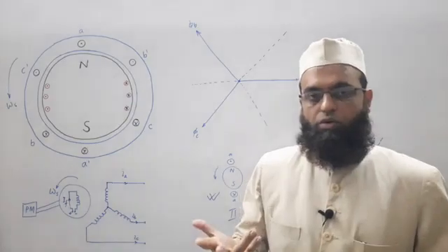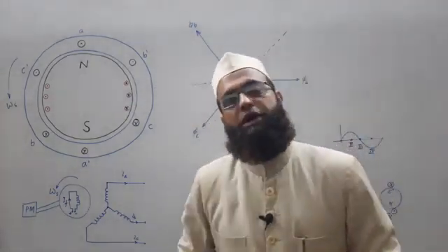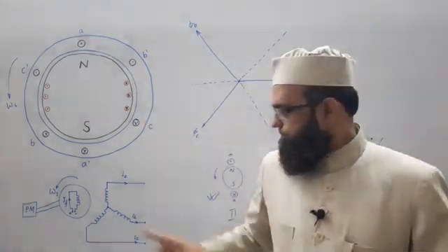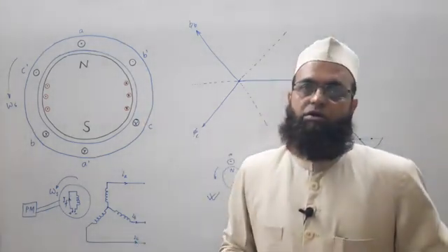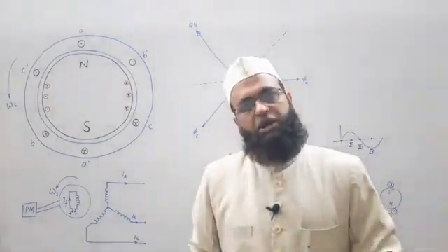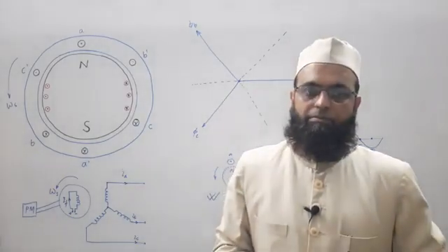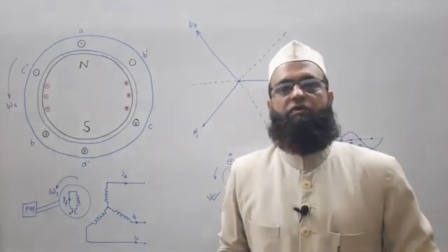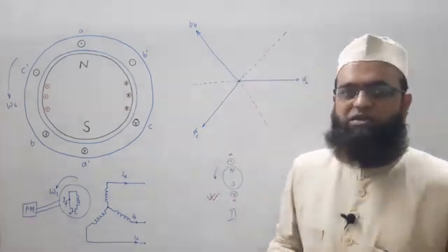Now we have three phase balanced currents flowing in the three phase balanced winding, IA, IB, IC, once load is connected. These three phase balanced armature currents will produce a rotating magnetic field as discussed in case of induction motor. We know it very well how a rotating magnetic field is produced, that is a separate topic.